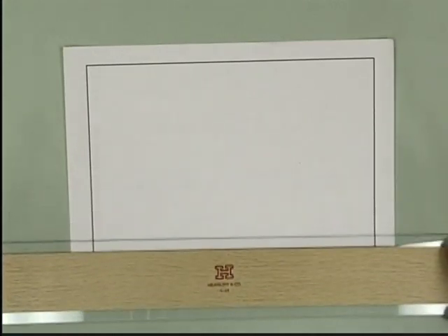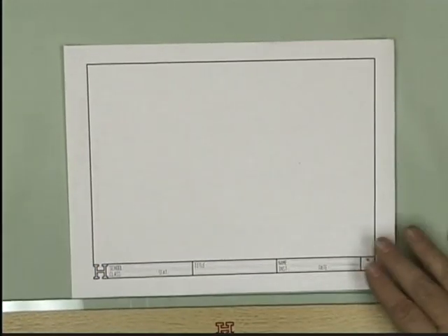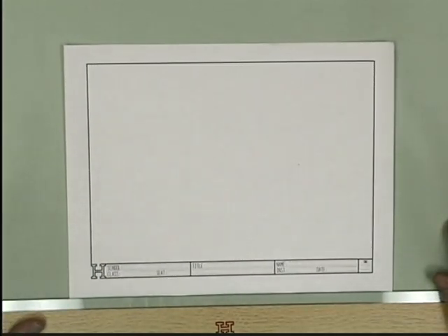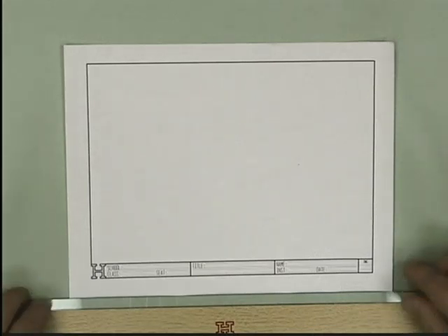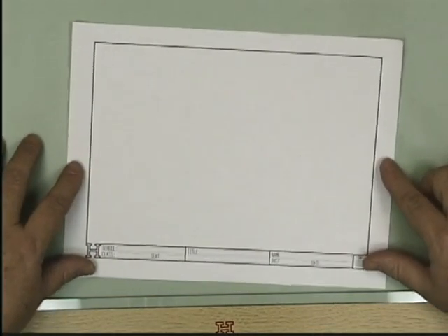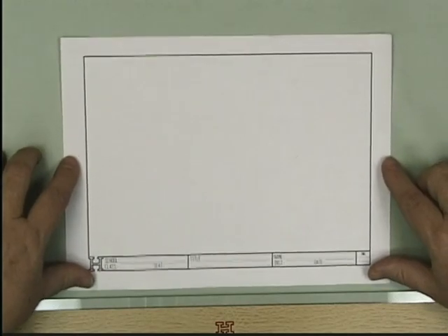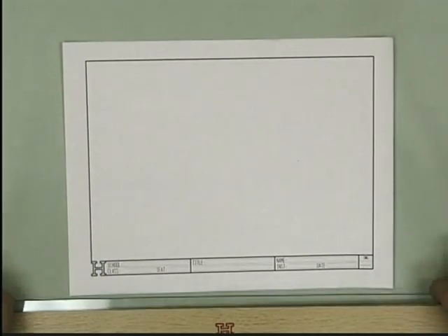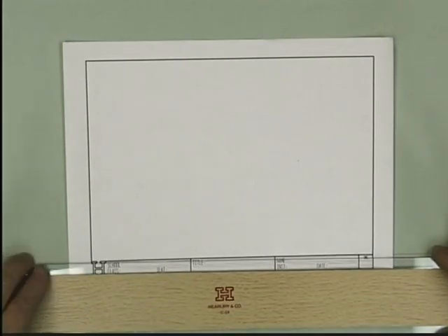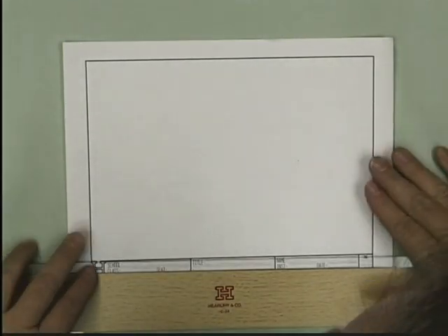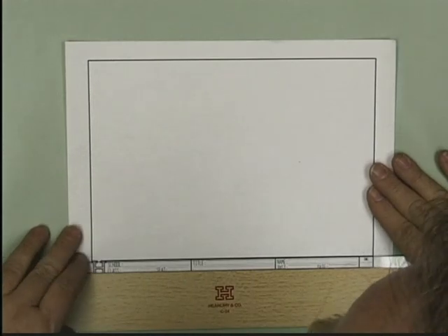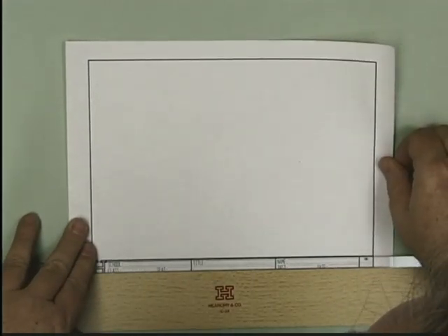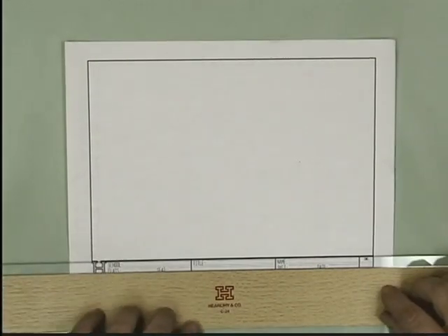And I want to line the paper up with the top edge, or the horizontal edge, of the T-square. But I don't want to line the edge of the paper up, because after all, this pre-printed form was run off thousands at a time in a high-speed press, and the paper might have gotten cut a little crooked compared to the lines. What I really want to do is line this up with the lines on the paper, not with the edge of the paper. So I'll very carefully adjust this until the top edge of the T-square is exactly aligned to one of the horizontal lines on the pre-printed form.